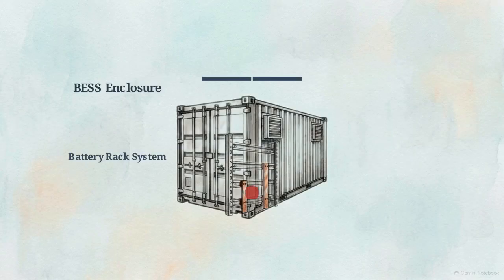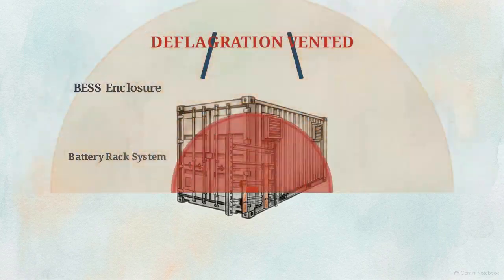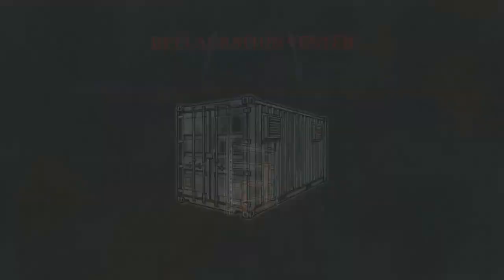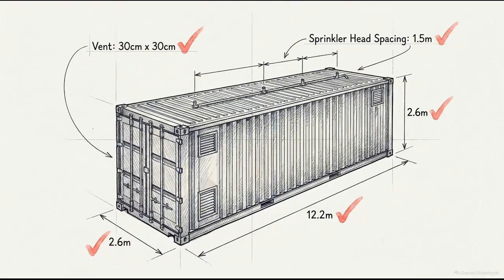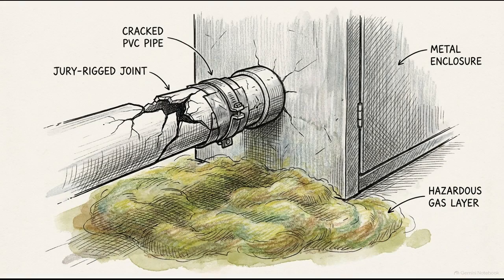If ignition does occur, the system relies on a dual requirement. Explosion panels blow open to vent deflagration pressure, while listed water demands are applied externally to cool adjacent exposures. Every dimension, vent size, and sprinkler spacing must precisely match the unit's specific UL test evidence. Improvising purge exhausts spreads flammable gas unpredictably. Best survival relies entirely on exact physical compliance with tested containment parameters.